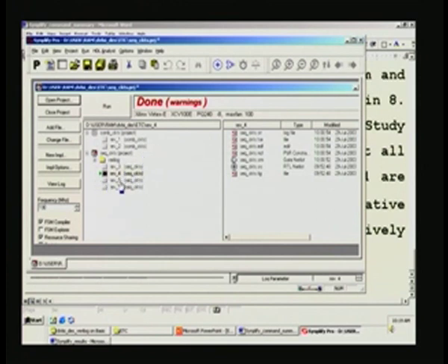So here I have already made 2-3 revisions, so that I can expedite the explanation and not repeat the same thing over and over again. The same file is being used for all the revisions, and this is for sequential circuits. If I click on revision 3, it says XCV50E, and the package is 144 pin with a -8 speed. And if it is revision 4, I have XCV100E. This is the Virtex highest speed possible, and this -8 is the highest speed, I hope so. We will have a look into the results, then we will know whether it is so.